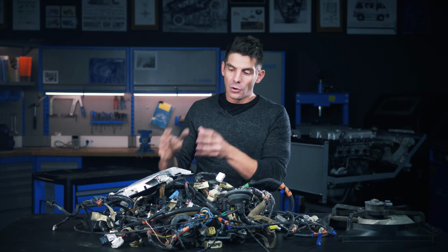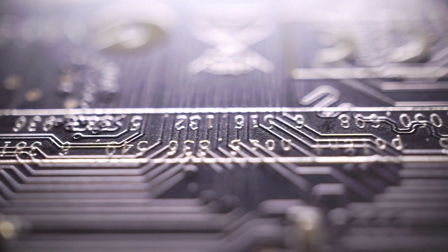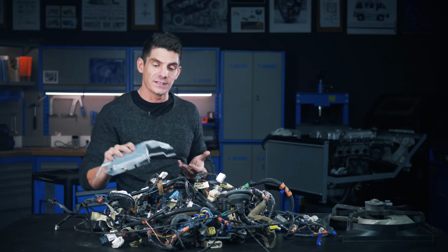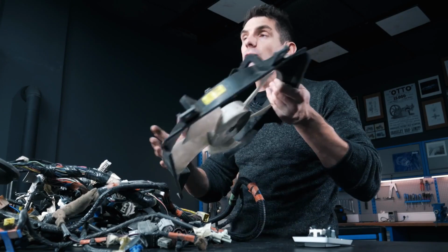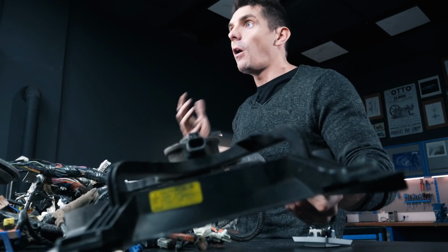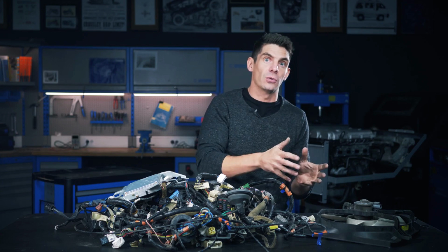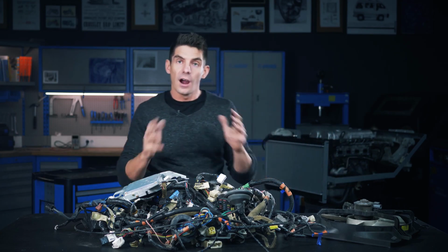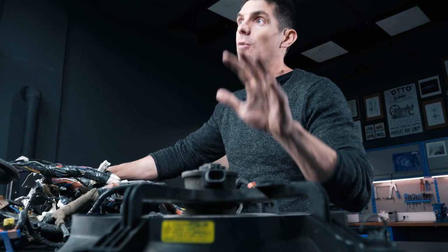When we talk electronics, we're normally talking about low currents and low voltages, little wires, thin wires, and traces around a circuit board like what's inside here. Now, electrical or electrics, that means usually bigger currents and thicker wires. And relays are often the interface between electronics and electricals. So, as we've seen, a relay sits between this electronic ECU and the electrical fan.